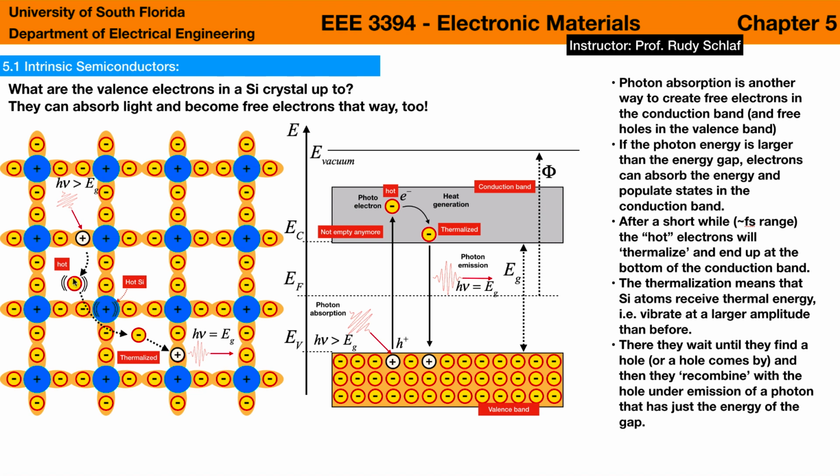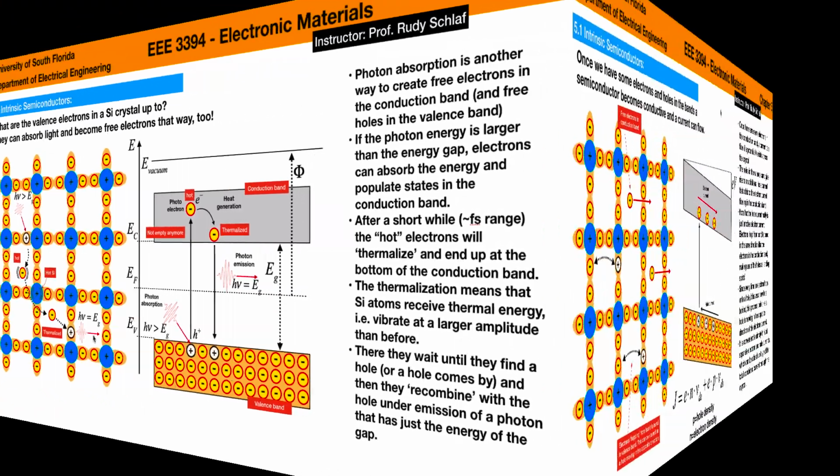The electron is hot, right? It has this energy now above the conduction band minimum. And then as it travels through the crystal, it passes its energy on to the crystal atoms, only to continue to move about at lower energy until it comes close to a hole, and then it can recombine, and that photon with the energy of the band gap is being emitted.